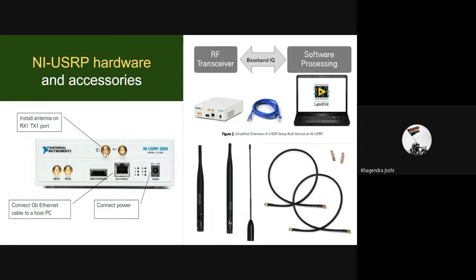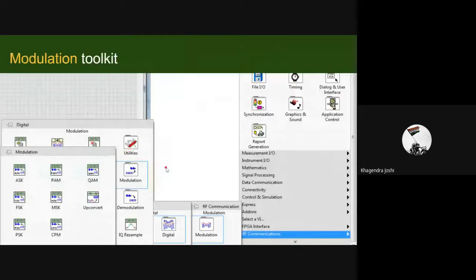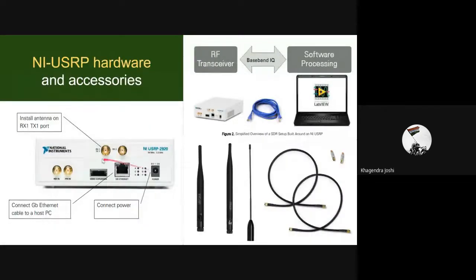So whenever you want to design a transmitter code, in that case you have to connect the transmitter USRP with the antenna to the TX port, right? And the USRP which you are using for the receiver, there you can connect to any one of the ports, right? So definitely two different USRPs will also be required to create such a setup, right?